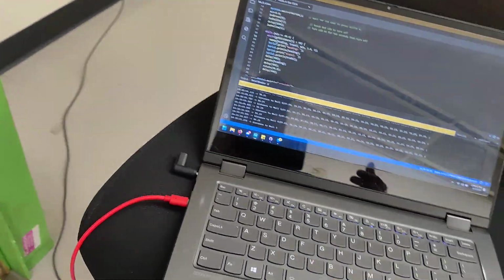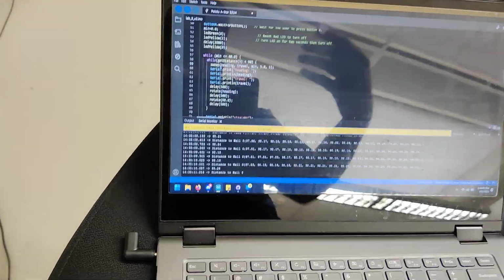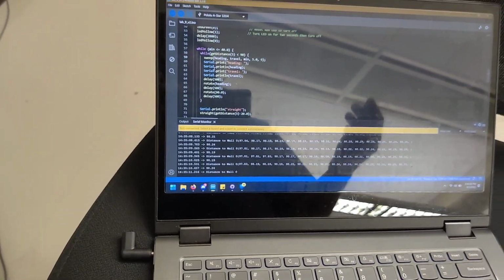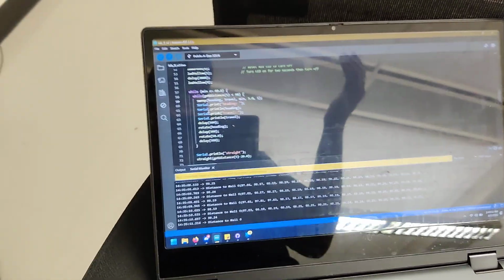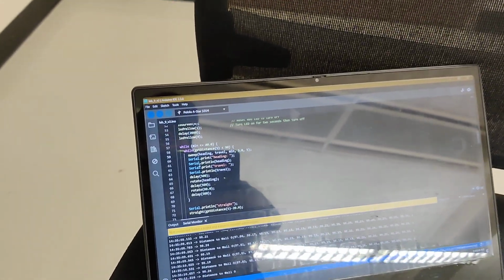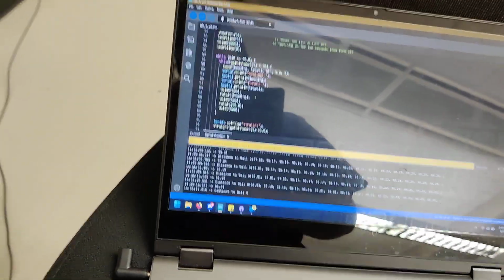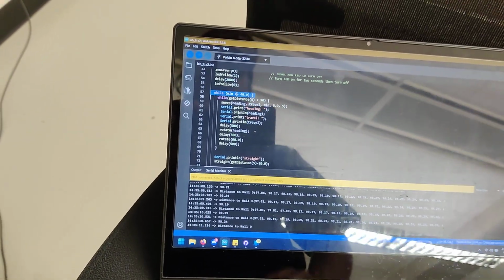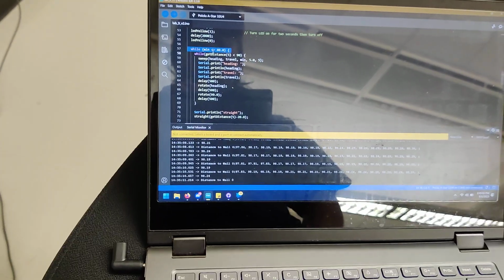Once we come out to the open area and there's nothing within 40 or within 4 meters, my get distance value will automatically return this min value of 41. Because we can't differentiate between our lowest value, if something's too close or if something is way too far, my default for if get distance finds absolutely nothing is 41, so that will break us out of this in case we get to the exit. So this while loop is looking for our exit case if nothing's within 40.